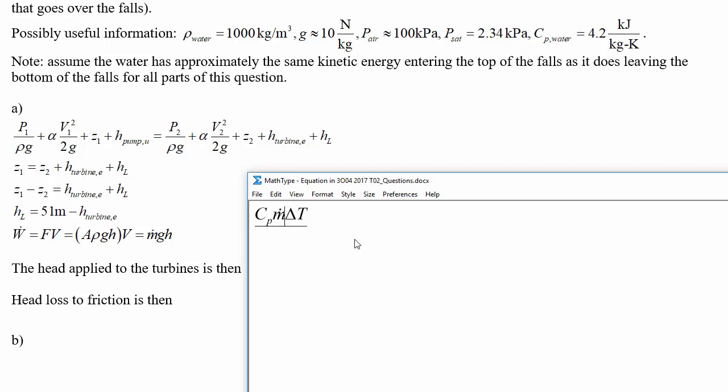So if instead, in the case of fluid flow, we have a mass flow rate, then what we're going to be getting at the end is not an energy, but a power or an energy flow rate. So that is what's going to be equivalent to our standard energy flow rate term, the power term associated with a certain head loss. So this gives the information for how we can translate that head loss term into a temperature change.